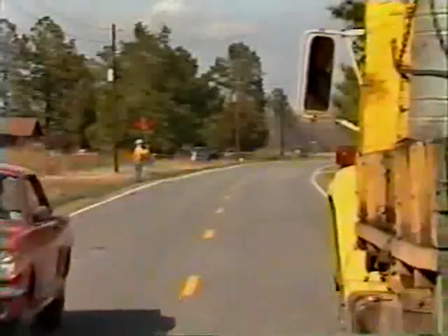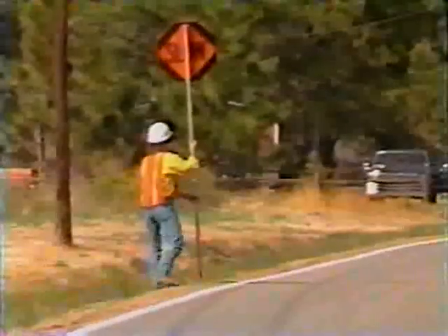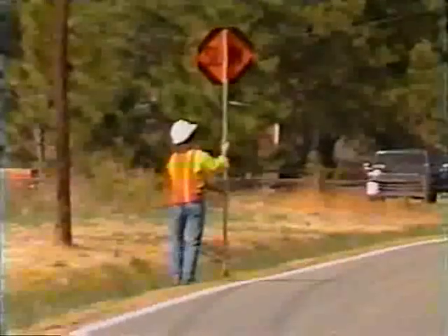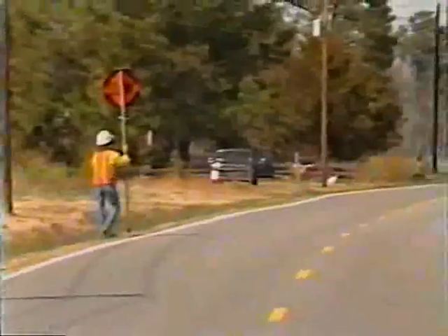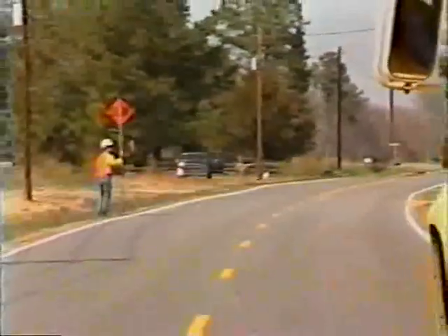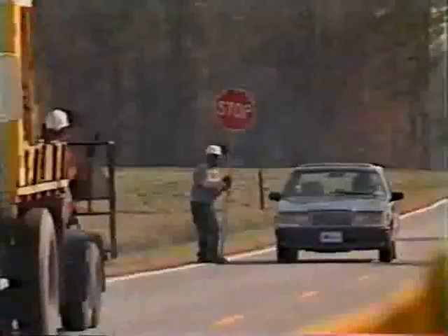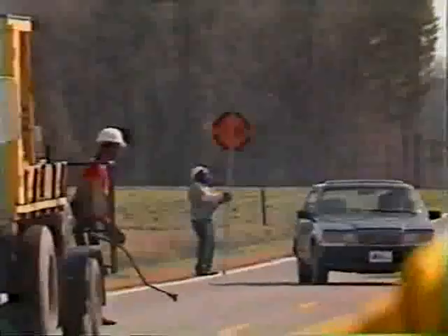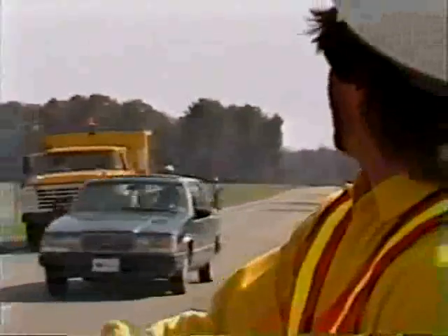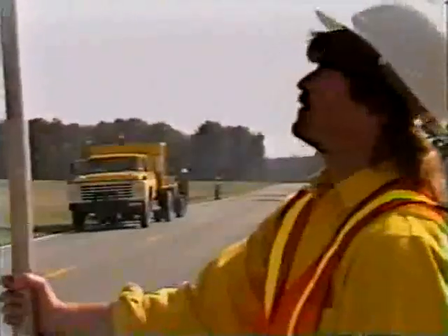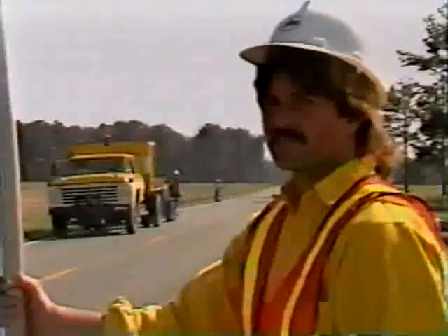Station flagman 200 to 300 feet ahead of the work activity. The flagman should stand on the shoulder adjacent to the traffic lane that he is controlling. As the operation moves, the flagmen also move, maintaining 200 to 300 feet between them and the work zone. The two flagmen must have clear sight of each other and be in total communication when directing traffic through the work area. On occasion, a third flagman may be required due to poor sight distance or intersections.